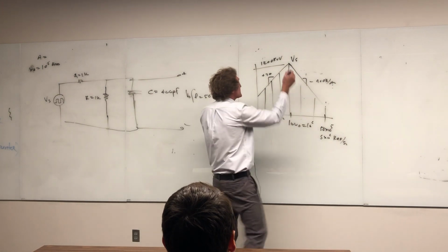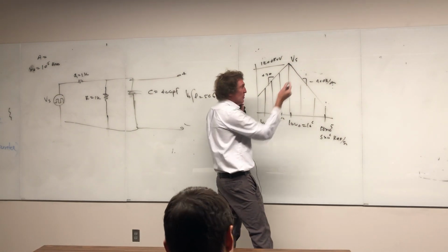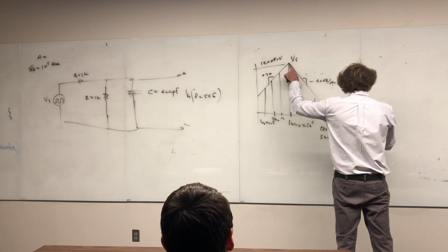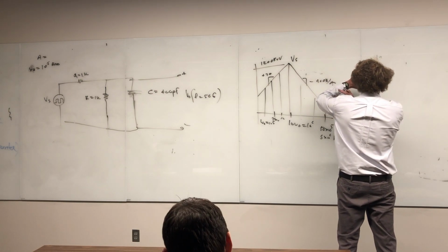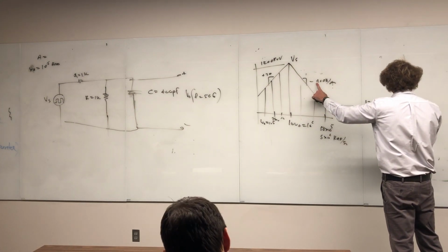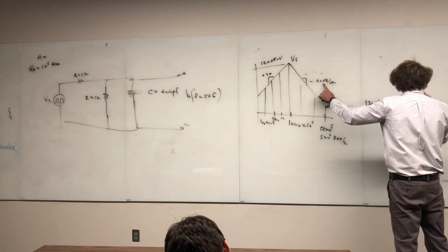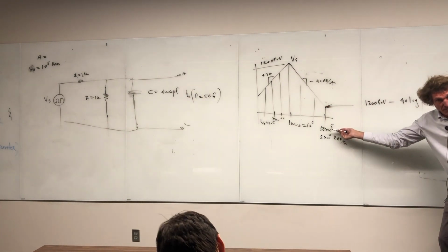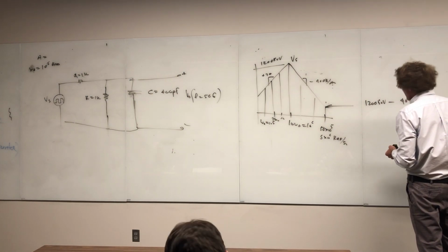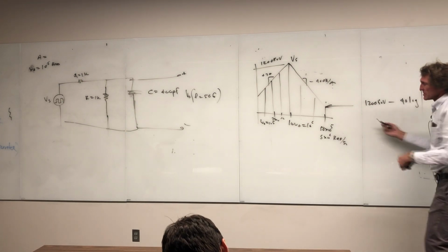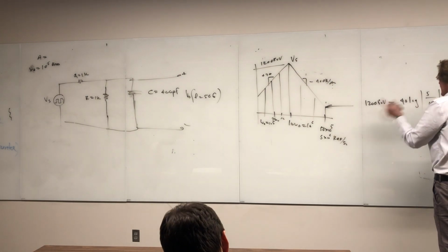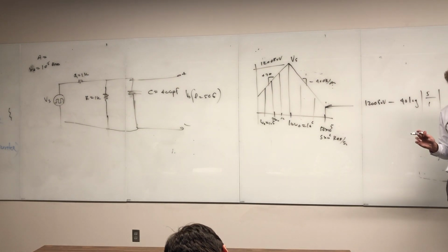What would that level be? Think about it. This is 120 dB, right? We're going down at 40 dB. To get the level here, we start here, right? We take 120 dB, oh my gosh, dB microvolts, and we subtract minus 40 times the log of what, people? The frequency you stop at, right, which is 5 times 10 to the 6th, over the frequency you start at, which is 1 times 10 to the 6th, or just 5. So that's the value here of the input, right?